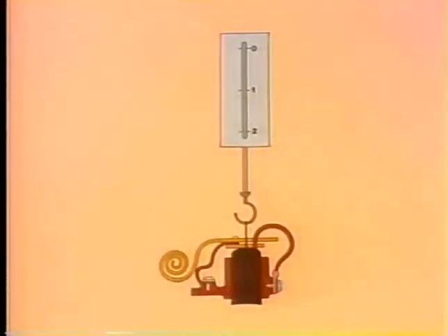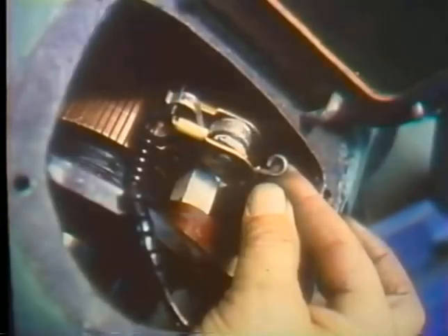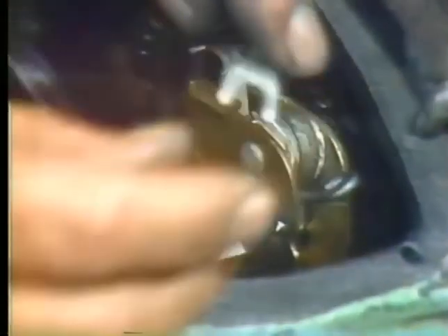After you've found out what it ought to be, you can use a brush tensioning scale. Attach the scale to the tensioning arm and pull until the brush just clears the commutator. Then read the scale. Adjust the tensioning device until you have the correct pressure. Now connect the brush pigtail to the brush rigging and make sure the connection's tight.